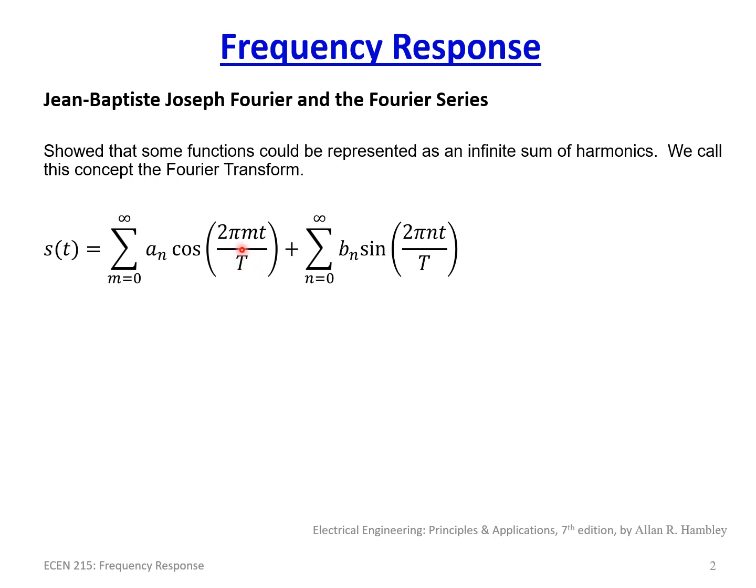So we have this frequency component, and it has a different amplitude for each one of these. And the idea is you end up with A and B, and of course this changing value of m, and you end up being able to replicate any signal with just different sine and cosine components.